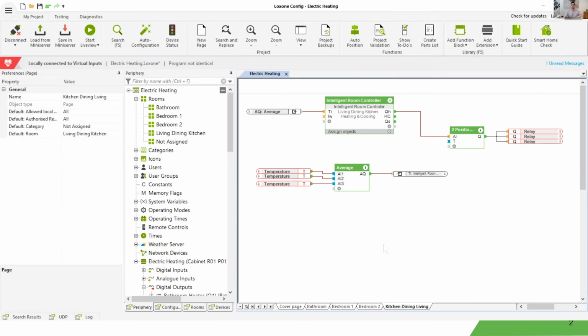The only extra thing you may have to consider in something like this, which is essentially an infrared panel array, is that infrared panels have a habit, when there's a lot of them, of doing things like tripping MCBs and tripping RCDs.